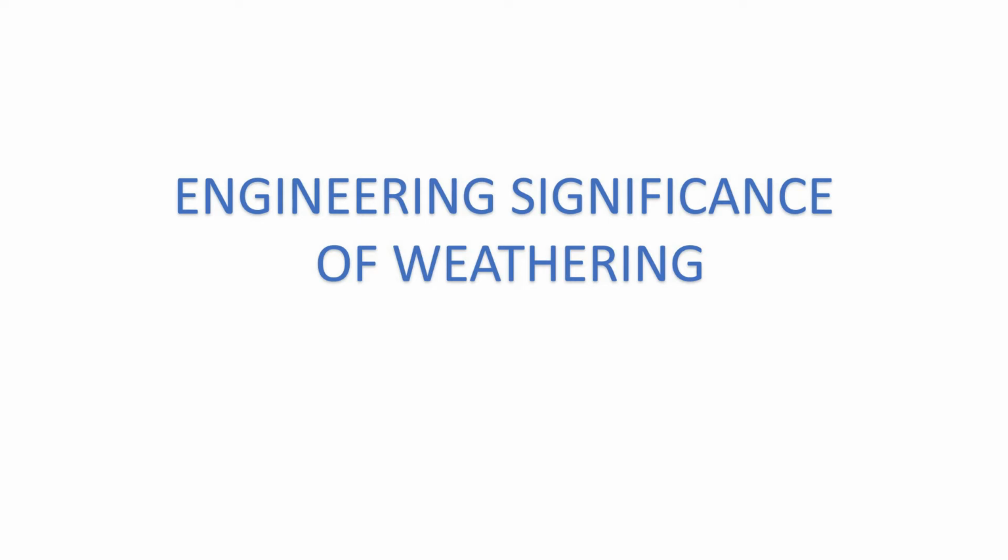When foundations are to be laid down to the bedrock, the depth of the weathered cover has to be found out. The degree of weathering is to be known, and the trend of weathering in that area definitely has to do a lot with the ultimate safety of the project.